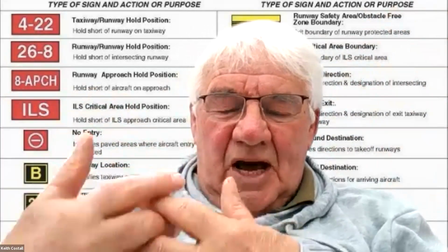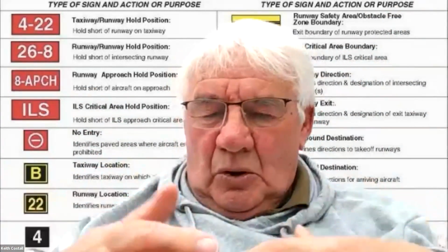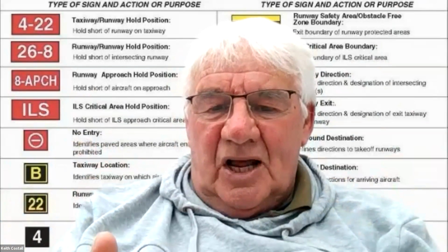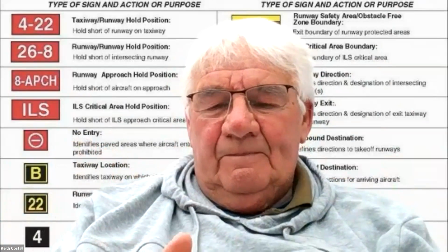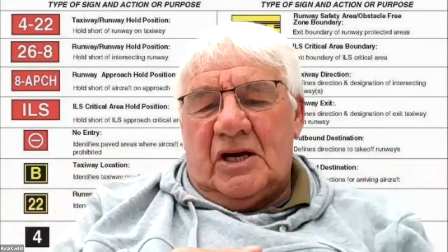And then that becomes a discussion on, is it 1 gigohm or 2 gigohms for a new installation on a new project? What are your thoughts on that, Carl? Because I know you've done a lot of work on this area. It's been several decades, but I tend to follow along with David Rainey's point. When we worked with him in Memphis, the new cable installation should have a minimum value of somewhere between 400 and 500 megohms. That would be the minimum I would accept.